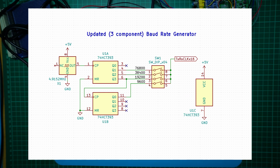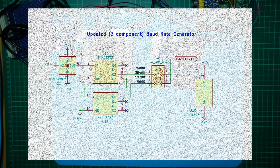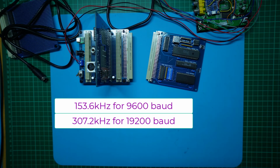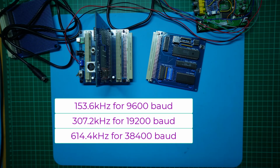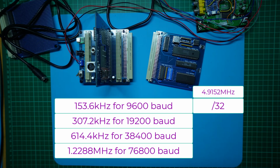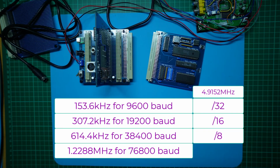Assuming we use the divide by 16 MC6850 clock option, that means we will need 153.6 kHz for 9600 baud, 307.2 kHz for 19200, 614.4 kHz for 38400, and 1.2288 MHz for 76800 baud. These frequencies equate to the 4.9152 MHz oscillator being divided by 32, 16, 8 and 4.